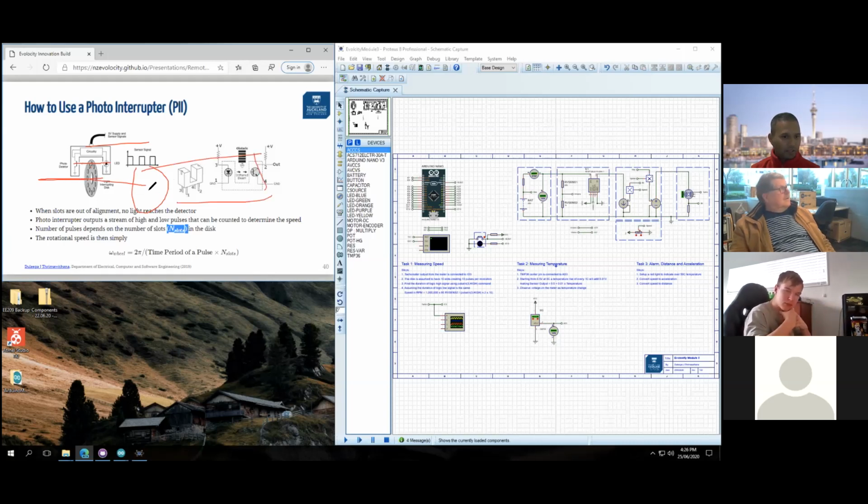And then this goes through the motor axis, and then this might be your wheel with the chain going around, and then you can figure out exactly how many rotations the motor is doing per minute or per second. And then you had to do some conversion, like Les said, because when this one does one revolution, your cart would have done, if you had a wheel that has a certain diameter, then it would have also done one revolution. Then you work out, okay, how many meters has it gone? And that would give you your speed of the cart, right?